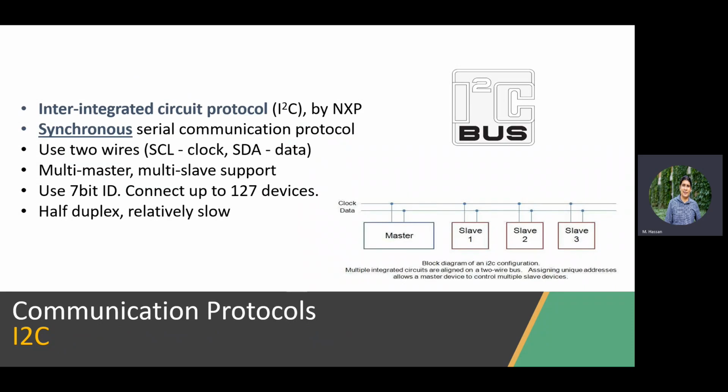which means the ones that are able to establish a connection. Why do people do this in embedded systems? Because you don't want your IO devices to pollute or bottleneck or cause a denial of service for your CPU. So the CPU is the one saying, I synchronize all of this. When I read data from you, I'm going to check it. You only interrupt me if you want, but I respond to this interrupt based on my own needs, right? So the CPU is the one that is handling all the communications.